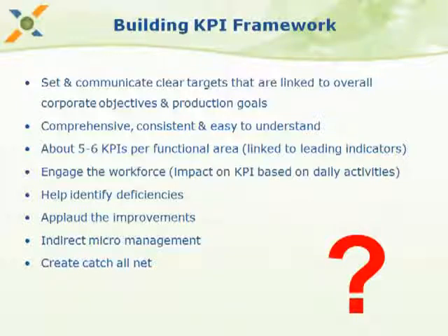There are two issues here that we were trying to identify. One is, of course, the data quality we talked about, but sometimes the CMMS itself is not collecting enough data or enough scenarios that can help identify some of these things. Based on what we have seen, some companies have started adding one more step within their work order life cycle. Once the work order is completed, before it is closed out, some companies have started doing a quality check on the work orders which are done on critical equipment.